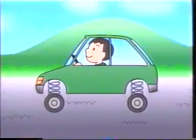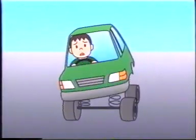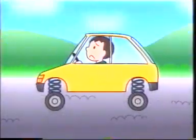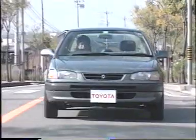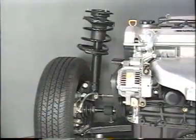But these functions conflict with each other. For example, if a soft spring is used to improve the riding comfort, steering stability will be reduced. And if a hard spring is used to improve steering stability, the ride will be uncomfortable. It is important to balance these conditions so that the suspension system matches the characteristics of the vehicle.